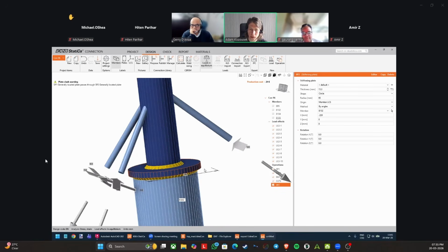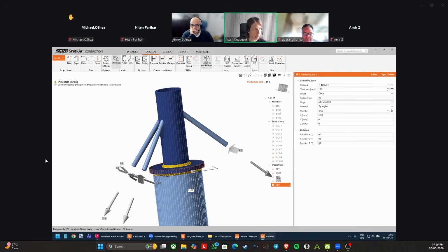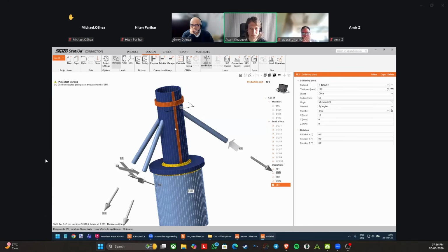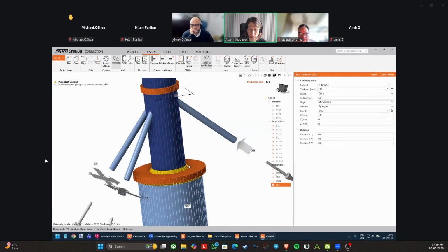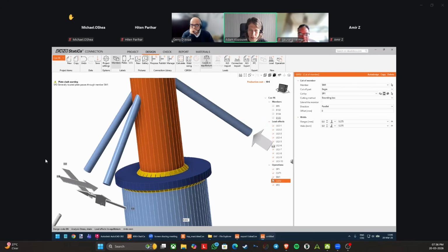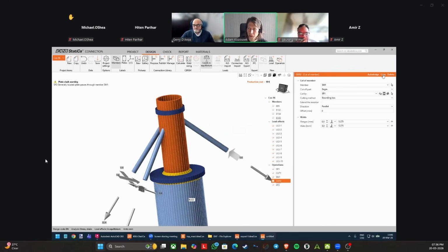Now you see the overlapping plate, and I want it a little bit higher by 10 millimeters, like this. And I want it smaller, of course, so I change the diameter to my project size. All right. Now let's get back to the other cut. So again, I can click in the tree, or I can click also, for example, on the weld, and it highlights the operation in the tree. And again, I copy this operation.